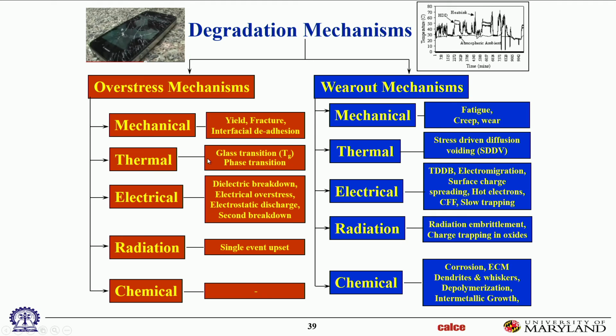And then as you go down vertically, I've separated the failure mechanisms out into those that are caused predominantly by mechanical stresses, those caused predominantly by temperature, those caused predominantly by either electrical current or voltage gradients, then those caused by high energy particles, typically in outer space, but it doesn't even have to be outer space. Any exposed electronics on base towers, cell towers out in the field, is constantly getting a dosage of cosmic high energy particle radiation, and they have to survive that. And then other kinds of harsh chemicals.